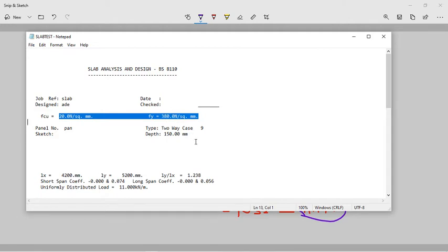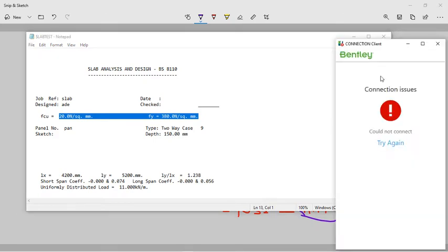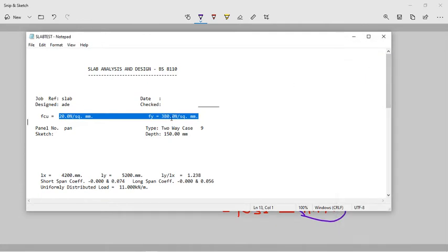Now another thing I want to stress is that the strength of steel in the Nigerian market in recent times is of questionable strength. So what I mean by that is that by the time you pick a sample of your reinforcement and you go for tensile strength test, you discover that most of the reinforcement in the market is of low strength.